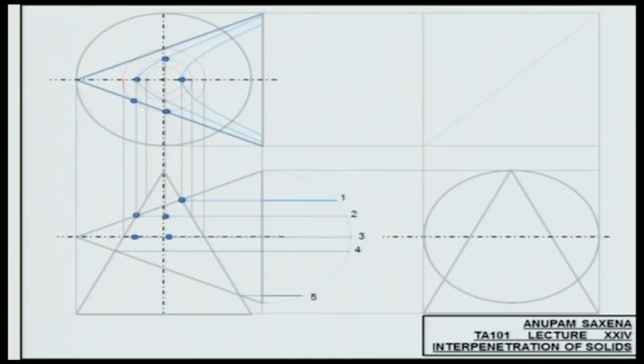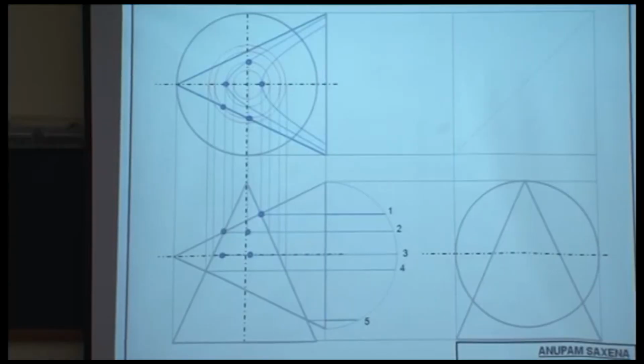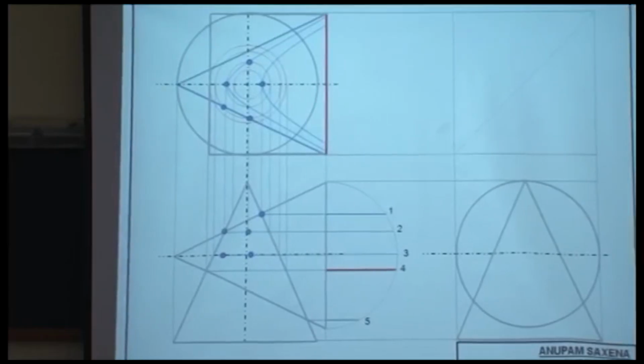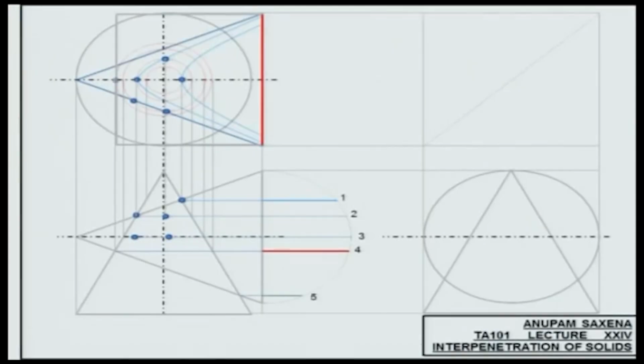Plane number 4, again, the vertical cone is going to be giving me a circle. The horizontal cone is going to be giving me a hyperbola. So you need to draw that hyperbola. I'll quickly go through that. So measure this distance, make that distance over there and over there. Okay, draw this box, the same construction procedure.